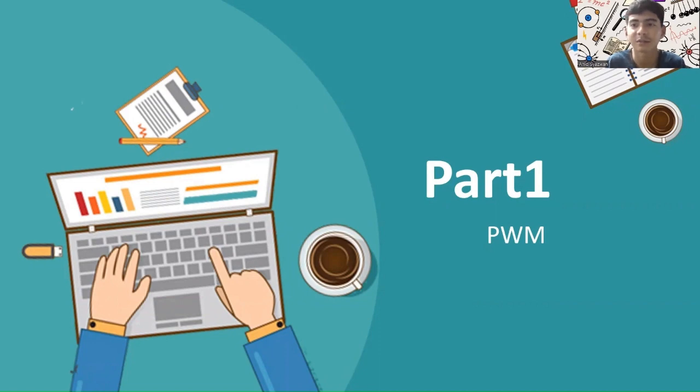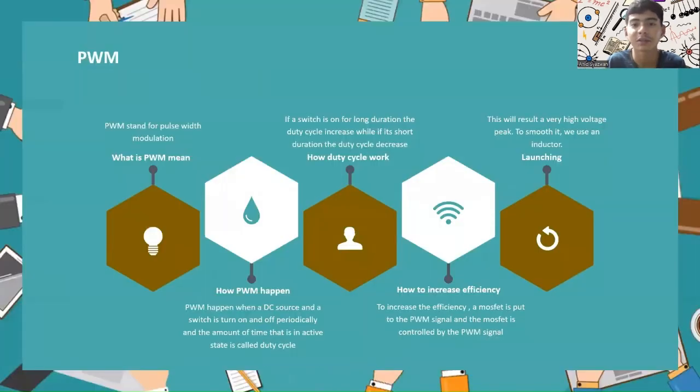Okay, let's start with PWM. If you have a source and let's say it's DC and it is turned on and off periodically, you will get a PWM signal. PWM means pulse width modulation. The amount of time a digital signal is in active state relative to the period of the signal is called duty cycle. If the switch is on for a long duration, the duty cycle increases, while if it's on for a short time, we call it duty cycle decrease.